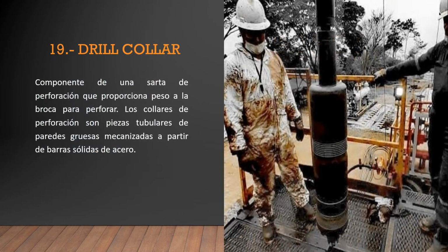The drill collar is a component of a drill string that provides weight on the bit for drilling. Drill collars are thick-walled tubular pieces machined from solid bar of steel, usually plain carbon steel.